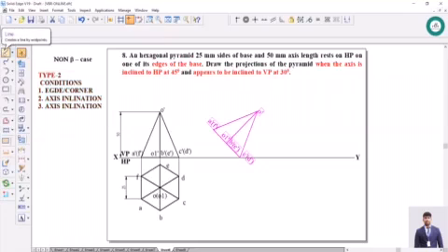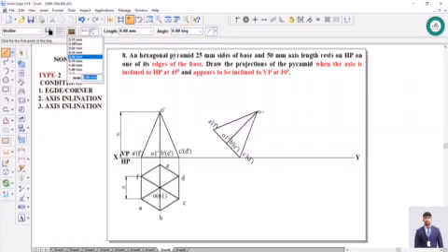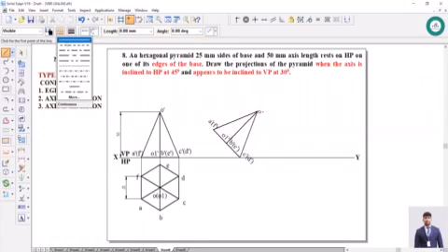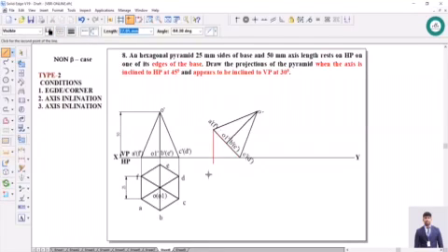After this, go to the projection line, take the suitable type and width. From all these points, project down. So while projecting, be careful about the end points. If the end point is not showing, you can go to the tools, IntelliSketch, relationships, and you can check there. So A falls on the first line and C falls somewhere here.